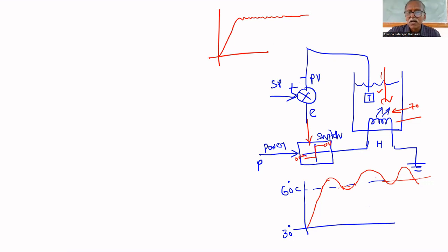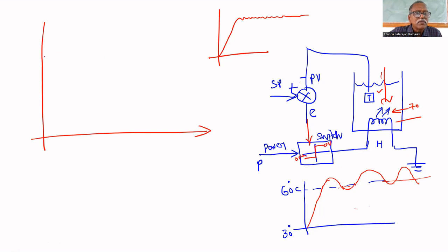It will wander. But I don't like this many on and off switchings, to avoid fatigue failure and chattering. Sometimes it may happen, that's why I want to avoid chattering. And for this, I am introducing a differential gap.